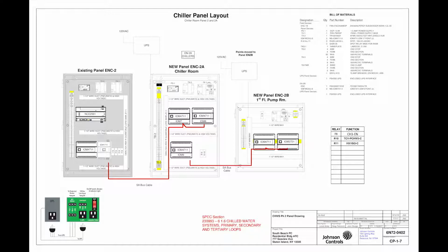So this panel, for the chiller plant, when I told you there was an NCE, that's like the brain, the controller. It's also got physical hardwired points to it. Underneath it is an IOM, which stands for Input-Output Module. So if we don't have enough point count on an NCE, we could put up to 7 IOMs on one panel. So that's added expansion for input-output. The red wire that you see there is the communication cable going to each one.